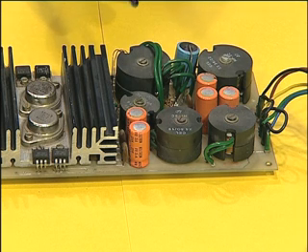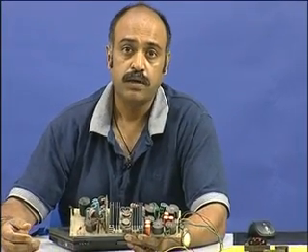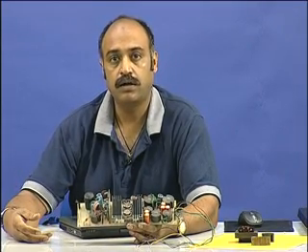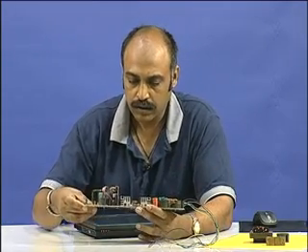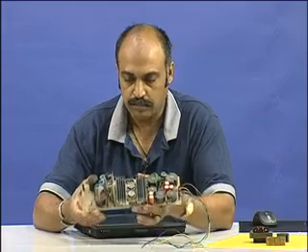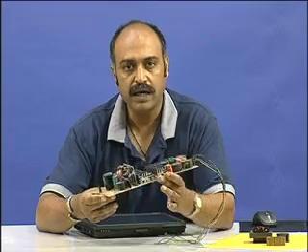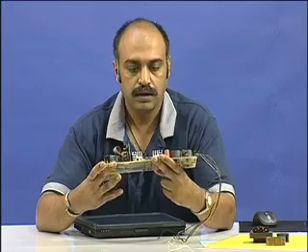Mu metal type of material can also be used for intermediate frequency range applications like 400 hertz to 1500 hertz and such. These pot cores can be used right from 20 kilohertz to 100 kilohertz, and in fact you have special ferrite cores which can go even up to 300 kilohertz, so on and so forth. Okay. So, these components arranged on the printed circuit board, which is just the function of a power supply here, will give you an idea of how the physical components are mounted onto the board and used in practice.